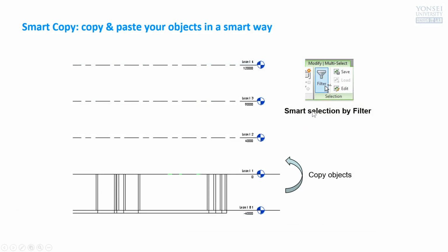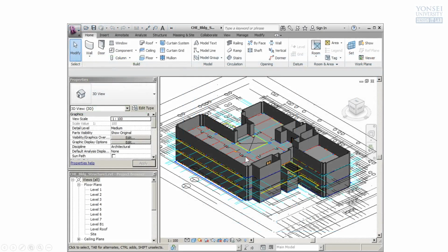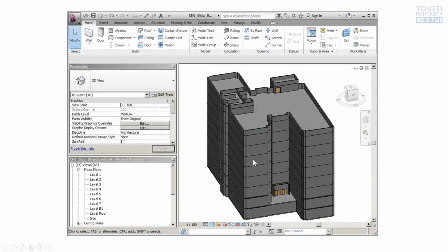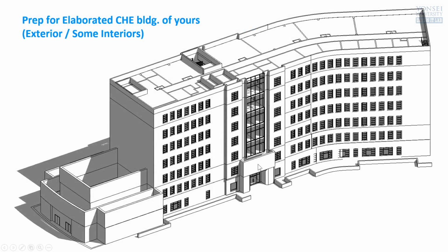The smart copy can be used for object regeneration for the entire floor, and then this kind of stacking is easily made using smart copy, and then finalized. How about this Samsung whole floor model, easily copied using the smart copy system to this entire building story.